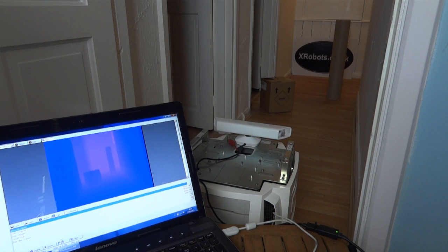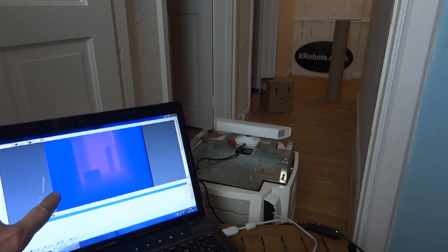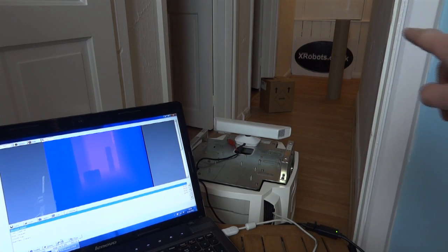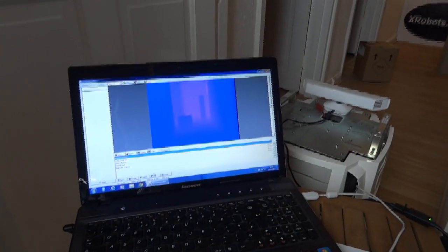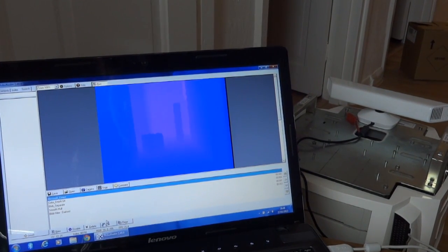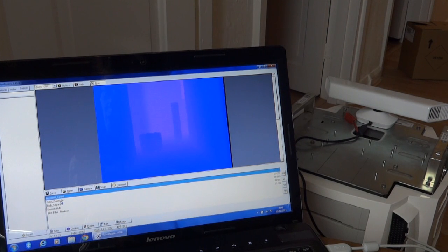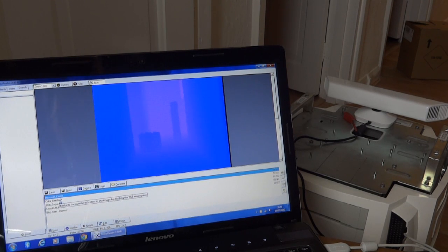So back to the depth colour image, which we can see with pink in the very distance and darker objects coming closer. There is actually more contrast than you can see here on the actual screen. I've put a couple of cardboard tubes down, a cardboard box down the hallway, which you can then see represented on the image there. There's, as I say, lots and lots of functions in RoboRealm. If you look at roborealm.com, there's a lot of documentation for each one. Literally probably over 100 different image processing functions, and all of them you can pull the variables out using the API to write your own code.